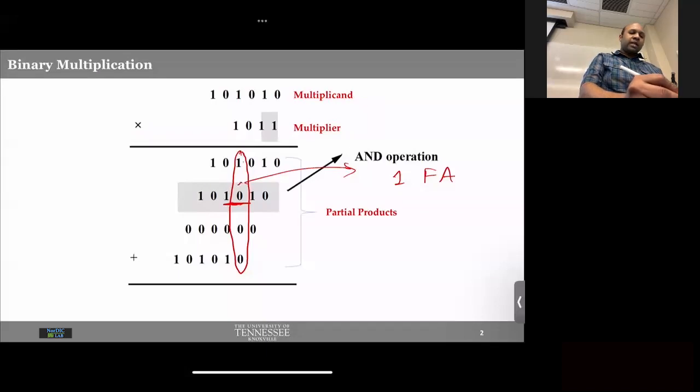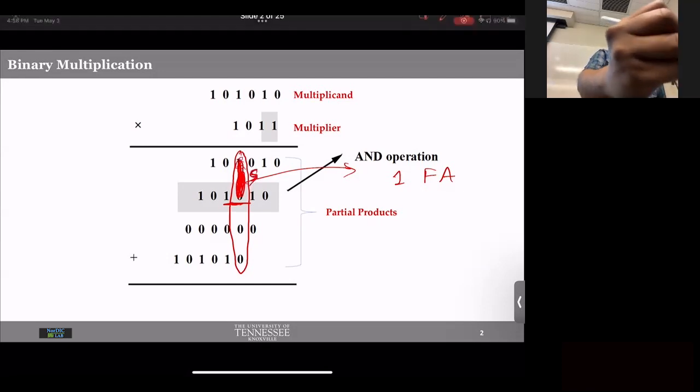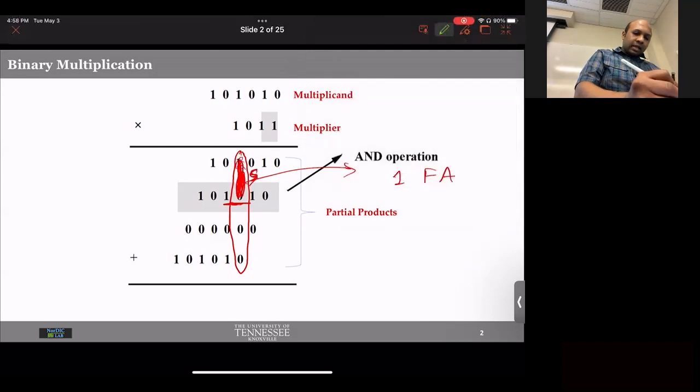And then what do you get here, by the way? By adding these 2, you get 1 bit. Maybe this is sum, S. Are you getting this? When you add these 2 things up, you get a sum bit, and carry will be given to the next stage. Okay, and then you add this sum with the next bit. You get another sum, maybe sum 2. You see the point? And then you add that sum with the next bit. You see what I mean by the next bit, right?